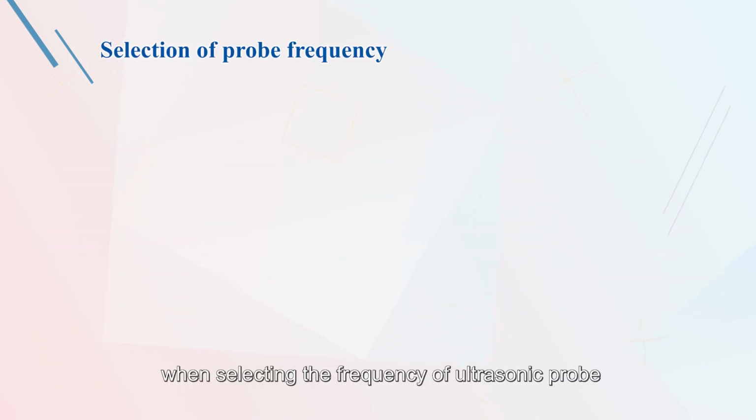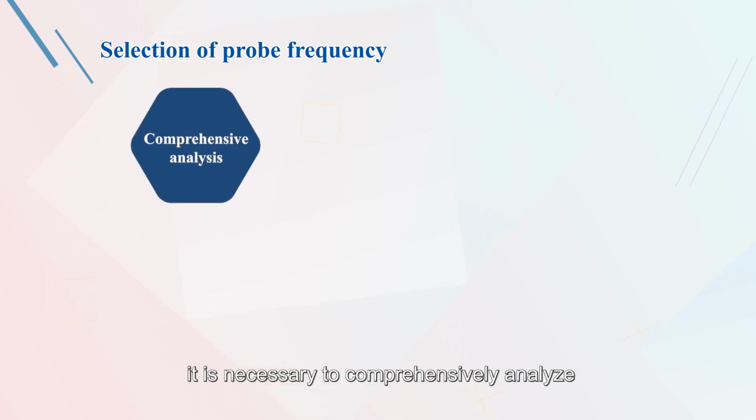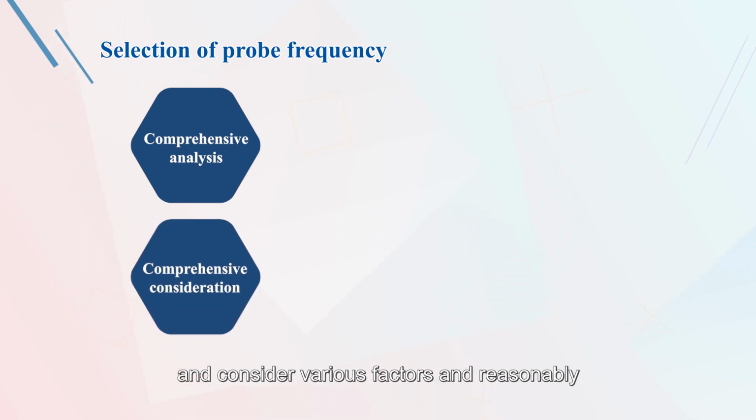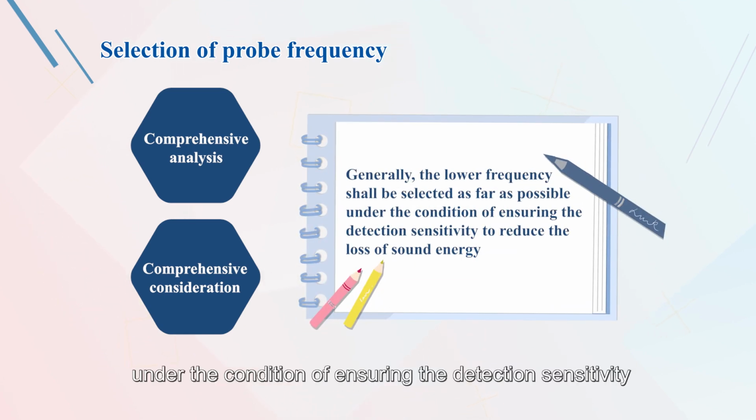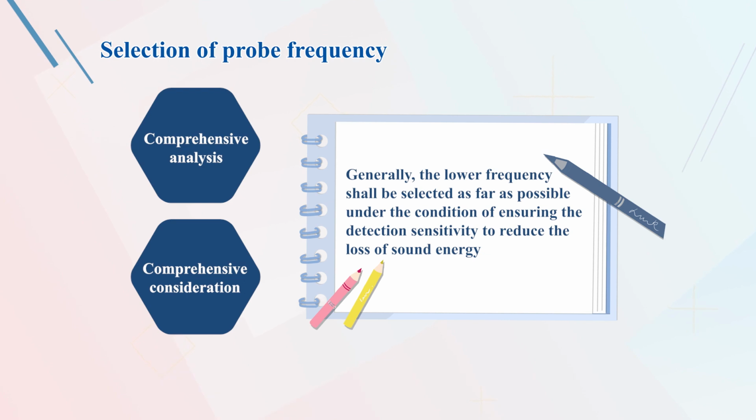Therefore, when selecting the frequency of the ultrasonic probe, it is necessary to comprehensively analyze and consider various factors and reasonably select the detection frequency. Generally, under the condition of ensuring the detection sensitivity, the frequency should be as low as possible to reduce the acoustic energy loss.